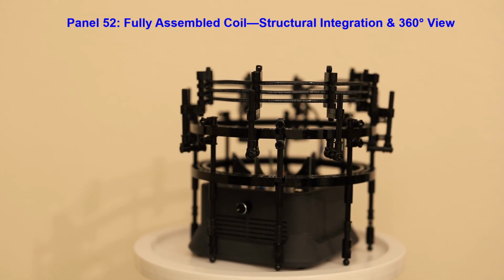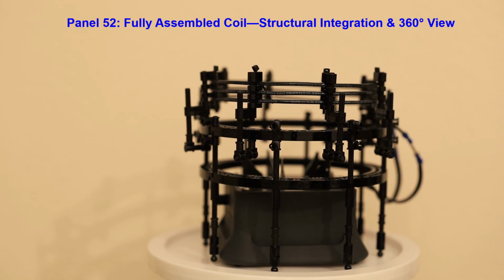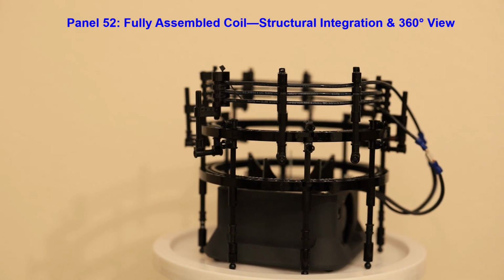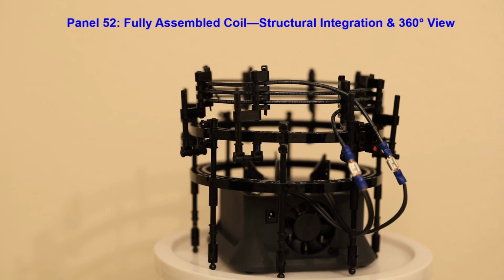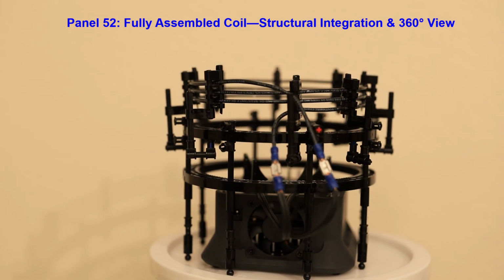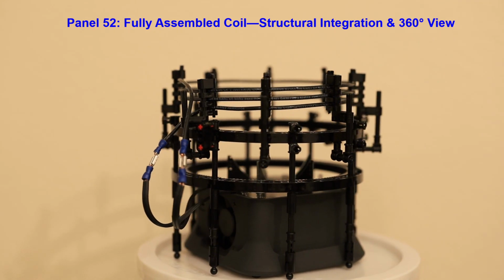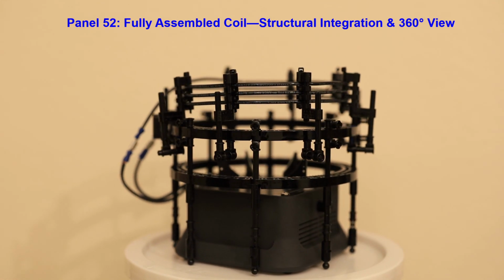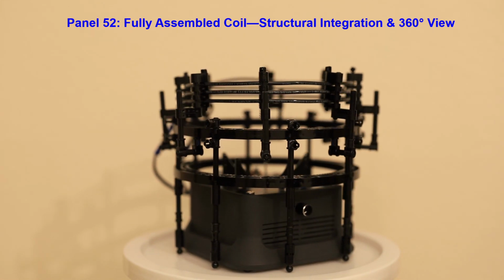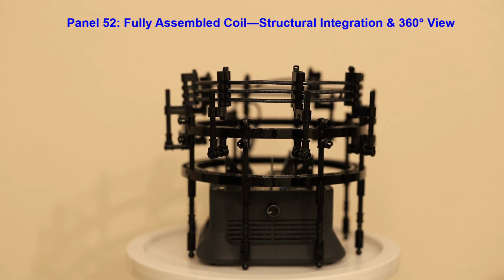To enhance adaptability, 18-gauge stranded wire connects the coil to the oscillator terminals using crimp disconnects for secure adjustments. The setup smoothly rotates, offering a 360-degree view of coil integration, spacing, and connections. Designed for optimal electromagnetic field distribution, this configuration supports precise plasma excitation and improved experimental accuracy.